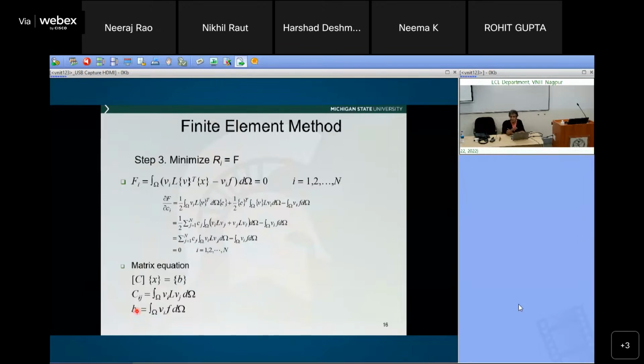In fact, when we do pulsed eddy current, the pulse is a pulse. If you take the Fourier transform, I know exactly what the Fourier components are. Then I do the finite element at each frequency and then take the inverse Fourier transform and calculate my time domain signal. That's a very, very common way of doing it. Yeah, you're right. You all know about the modeling, really. I don't think I need to spend too much time.